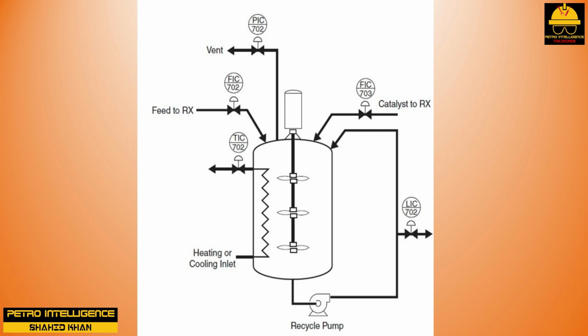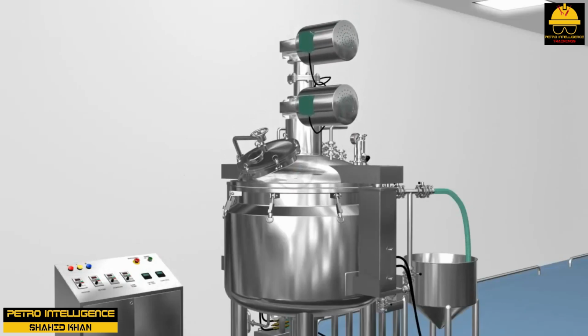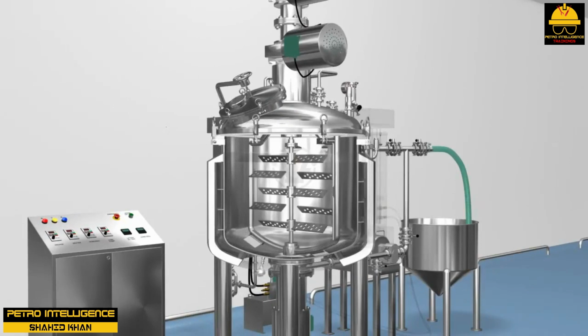Samples are taken frequently to ensure product quality. Stirred reactors are connected to off-specification (off-spec) systems that allow flexibility in switching between prime and off-spec situations. The automatic shutdown allows a technician to push one button and shut the unit down in the event of an emergency or runaway reaction.